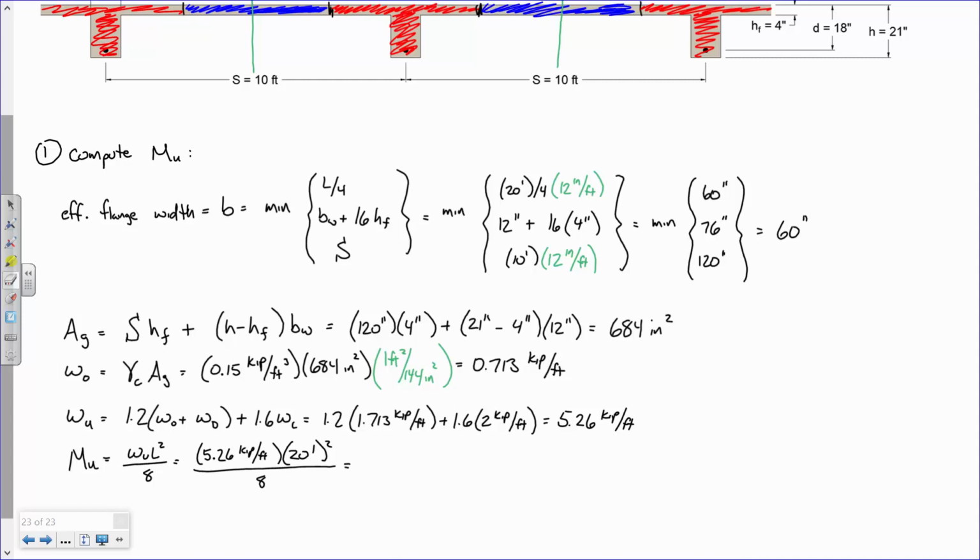So when did we do the 1.2 moment setup? Like, how we did it for the moments instead of the W's. When do you separate it? That's a great question. Here's when you separate it. You separate it when this is your dead load and that's your live load, because this is a distributed load, this is not. And if you try and take this and turn it into a distributed load to do this, I'm going to ask you to do that, and I'm going to go, bad.